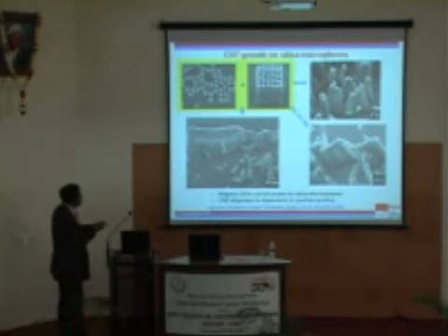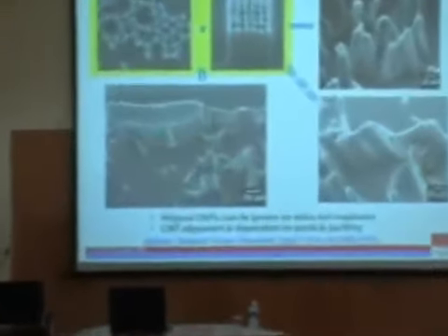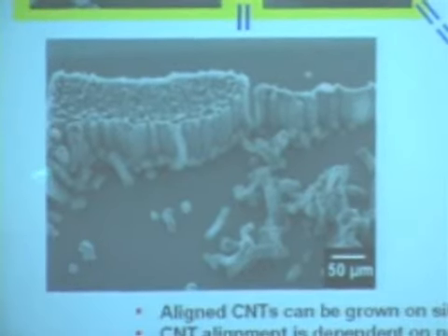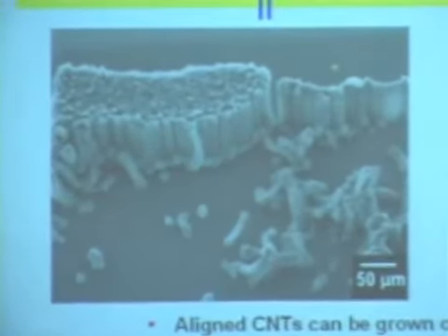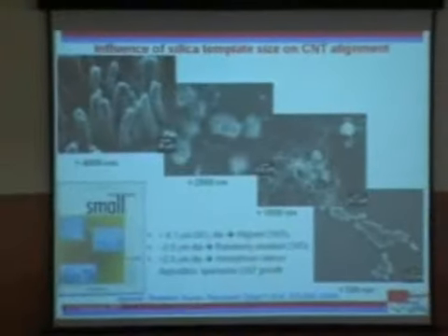Here you can see that the carbon nanotube bundles actually grow on the particles of silica, and also, in fact, inherit the shape of the assembly of the silica particles. You can get walls of the carbon nanotubes, or you can also get 2-dimensional assemblies like this without any problem. In cases where you have isolated particles, the carbon nanotubes growing fall down as opposed to being reinforced together. It's like soldiers all standing close together and reinforcing each other. Even if you have a weak one in between, you wouldn't be able to tell, he or she would be basically held together by the neighbors, by van der Waals interactions, actually.